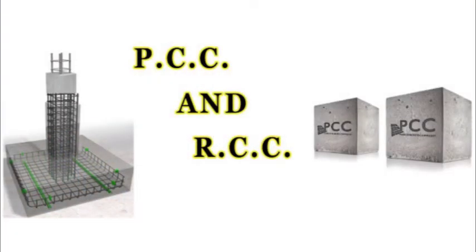Look, there are two types of concrete structure: PCC, that means plain cement concrete, and RCC, that means reinforced cement concrete. PCC means the one containing the basic materials of concrete, that is cement, fine aggregate, coarse aggregate, along with water. And RCC means the case in which we add steel bars along with concrete as reinforcement. Now, concrete may take compression and tension both, but concrete is very strong in compression rather than tension. So, to carry the tension, reinforcement bars are introduced in concrete, as steel takes tension very well.